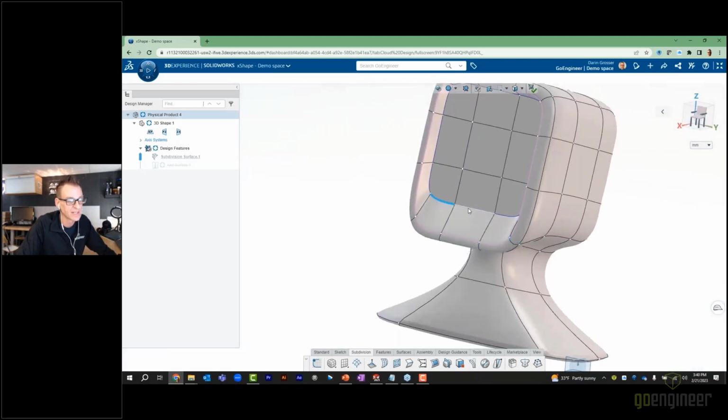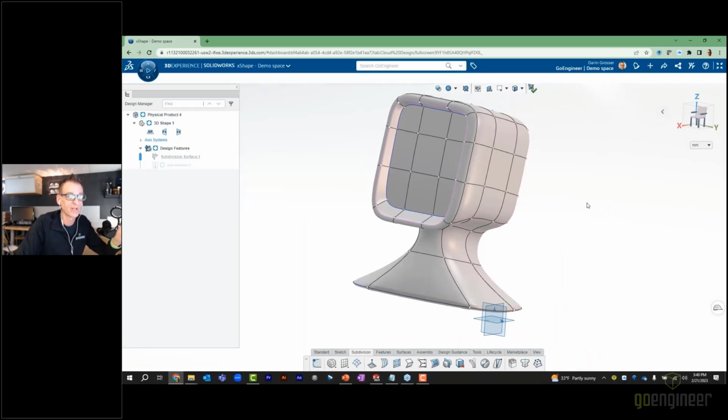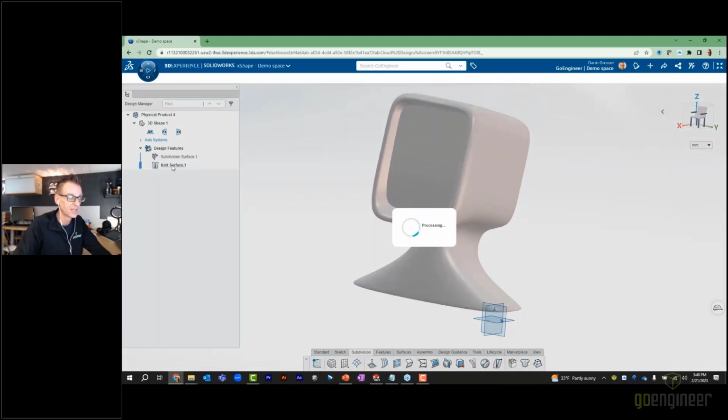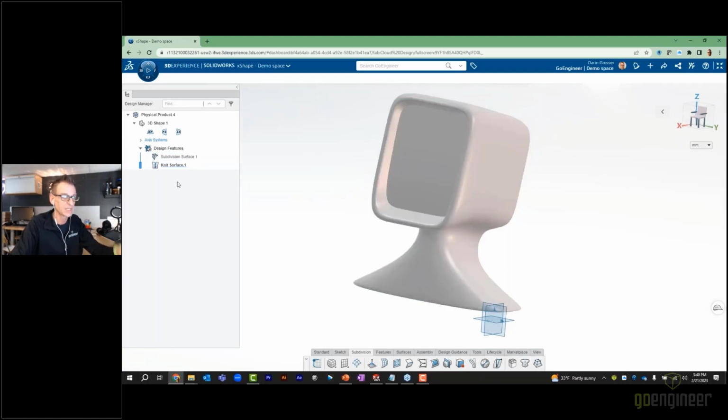What you have selected is all up to you, and everything moves in a way that you can go ahead and do some very, very nice what-ifs in order to create those. Now, I like to do what-ifs by actually exiting these bodies, going over here to the tree, and grabbing the sub-D body and actually hitting a Control-C, Control-V. That's a basic copy-paste.